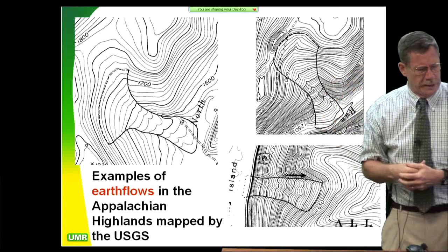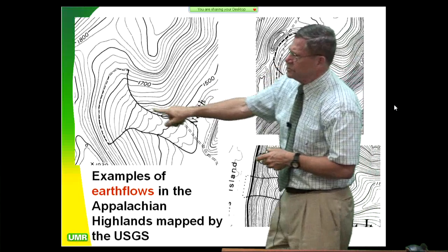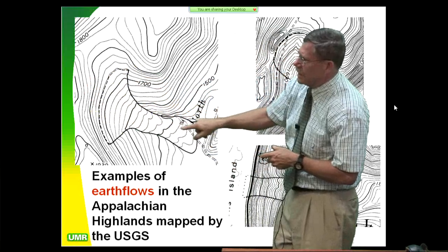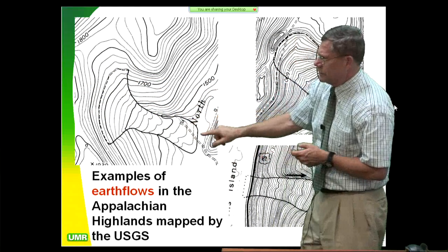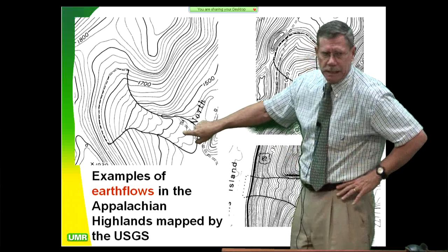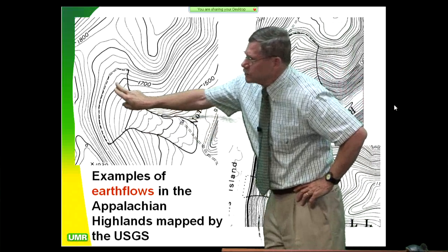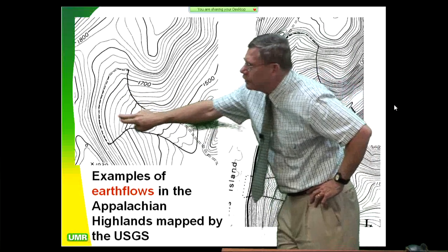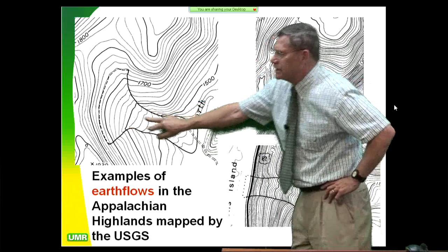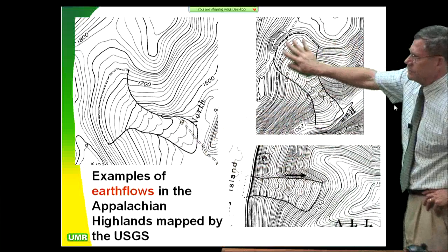You're just overwhelming it. And what you see are these kind of pear-shaped things like this coming around and all this debris. Now, if I came in here like that Contra Costa Road job and I drill a hole right here, I'm going to get 90 feet of slide debris. That's what you're going to get right here. What this is, it's one little earth flow over another, over another, over another, over the last 26,000 years, building up this toe. That's what all of them look like.